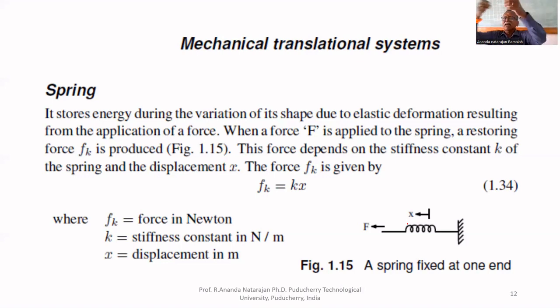So there are three wires, R, Y, B. One more is there, called neutral, but let us ignore it. Each wire has a different potential and generates a magnetic field. Each wire is in its own self magnetic field. Adjacent wires also produce magnetic fields. The R wire is in the magnetic field produced by B and Y. That's why it has the inductance effect also.